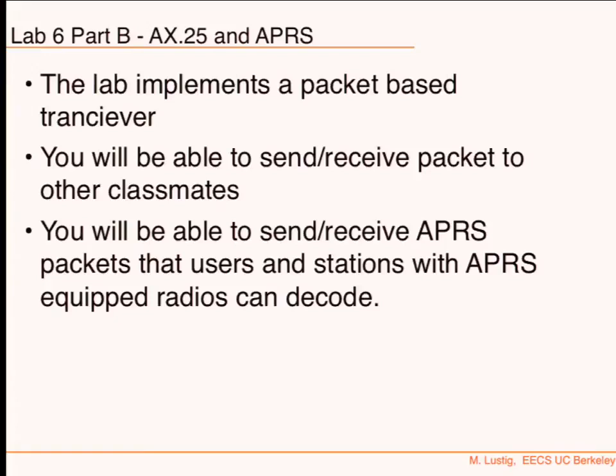Okay. So what you'll be able to implement at the end is you'll be able to send and receive packets to other classmates. These are going to be very particular types of packets that you'll be able to encode and decode. You'll also be able to send and receive APRS packets, which use AX25 to do something special. APRS is meant for mostly tactical, nearby local communication of packets, transferring information of where people are located, where cars are located.